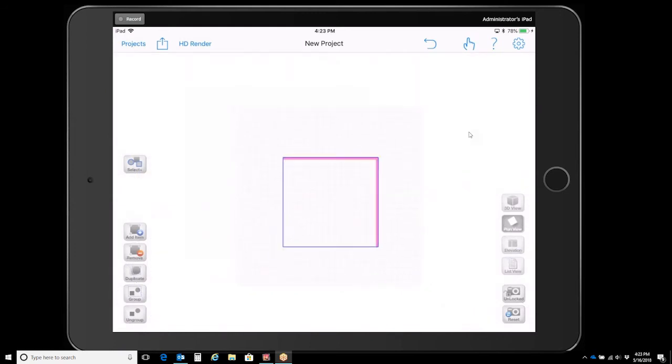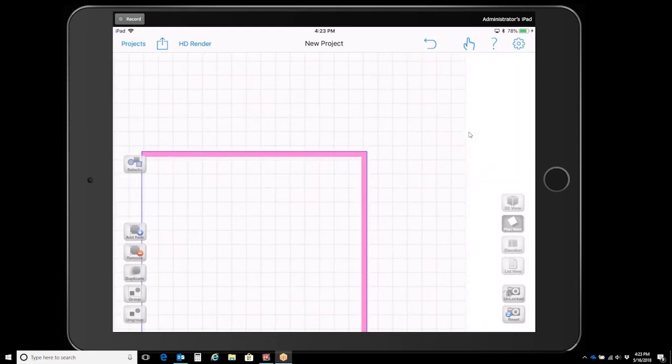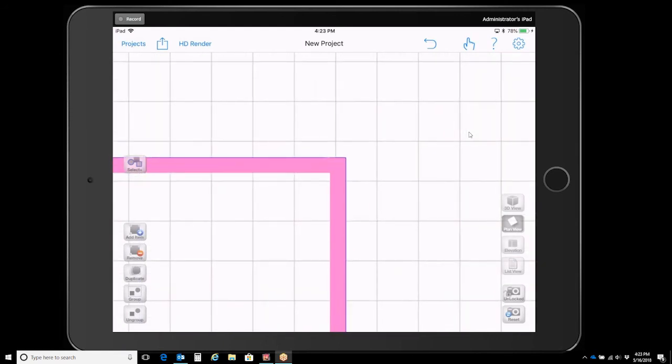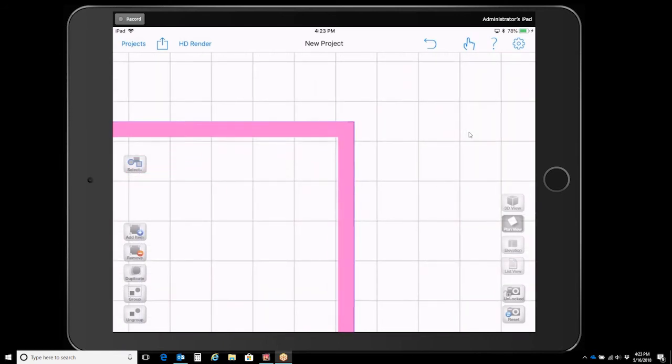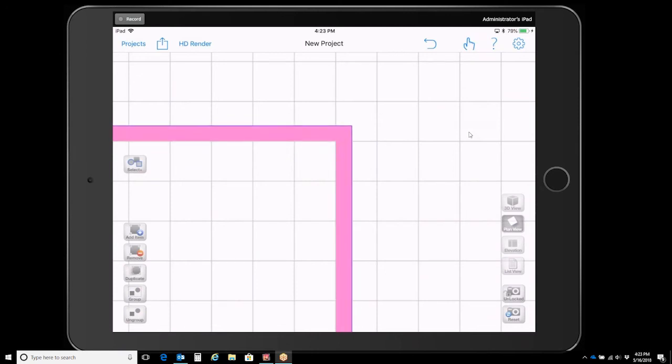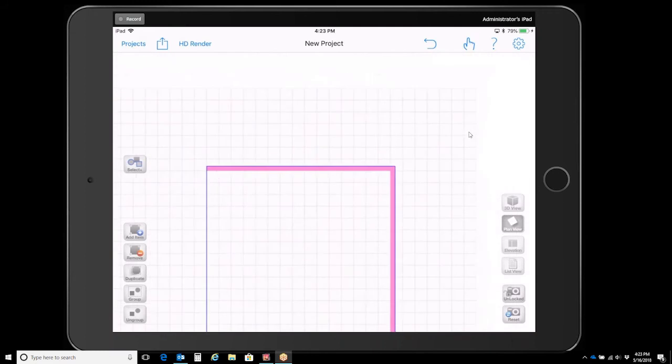And then I have these pre-built walls, 15 feet by 15 feet, with a curtain wall with a perpendicular drywall that's adjacent to it. And we do know that in our project, we're working with a 15 by 15 space. We know that drywall is on the right-hand side, so let's go ahead and use this curtain wall typical here.